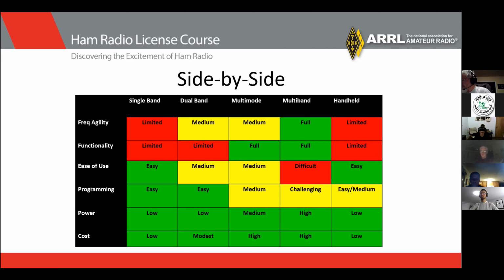Talk about that. There's 4 things you do to program your radio. First, you dial your dial frequency, and that is the frequency that the repeater's transmitting on. Then you make sure you have an offset, whether it's plus or minus. That's the frequency you're going to talk back to the repeater on. The third thing is you want your access tone. It's called a PL, a private line, a tone on it. You may want to make sure that you have the correct tone, because there's like 100, 103.5, 127.8, and there's about 40 different tones like that we use on the analog side.